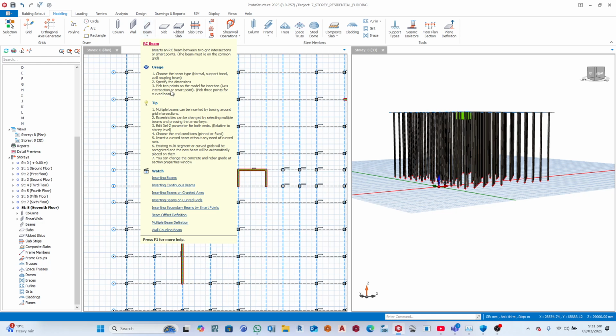Yes, it's very clear actually. For me, I used to use the generate option, but this is very clear. For columns, you don't generate, because if you generate, then you have maybe 100 columns on the 8th floor, 100 columns on the 7th floor, 100 columns on the... And then what that does is, when you begin to print out your reinforcement, when you go to design now, you are going to have a cluster between steel coming from this story, clashing with steel from this story, and so on and so forth.